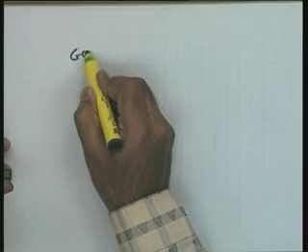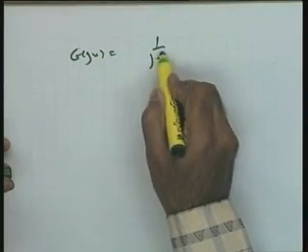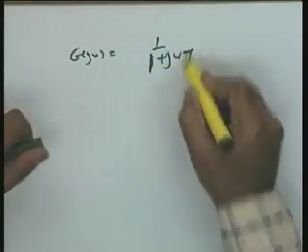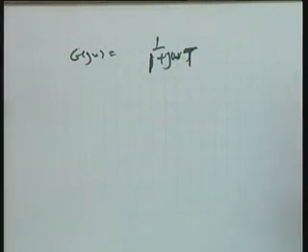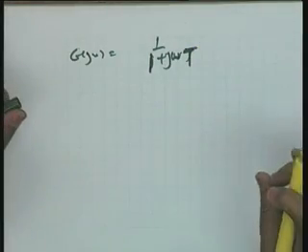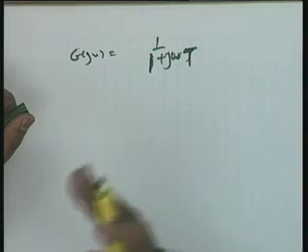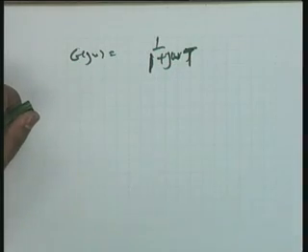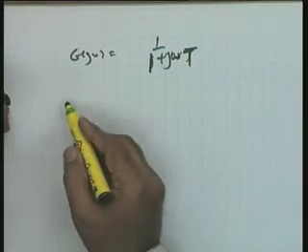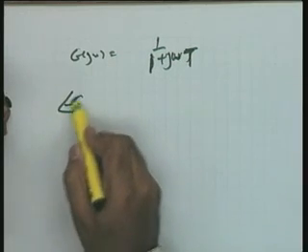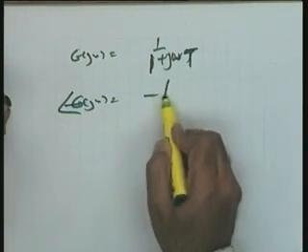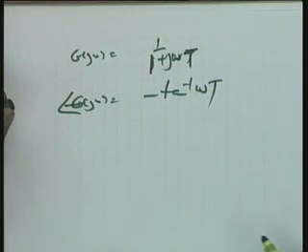Okay, I am left with a couple more. Oh yes, the angle for this, please. For the angle, I have to take G(j omega) equal to 1 over 1 plus j omega t. Now please see that if you look at different books, as far as the angle plot is concerned, different methods will be given. At least 5 to 7 different methods you will be able to find. Different methods means actually different approximations. What I feel is the following: angle of G(j omega) equal to minus tangent inverse omega t.